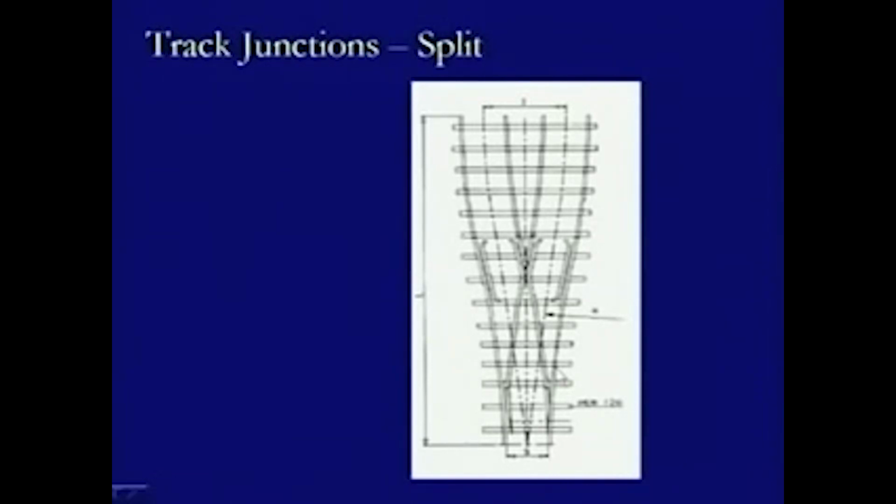than the interlaced sleepers. And here this is the center line of the main track, and this center line of the main track is produced like this, and therefore, at whatever angle it is taking a turn in this direction, the same angle is there at which it is taking a turn in this direction. And because it is symmetrical, we have only one point where the crossing is, and this is the V crossing being provided. There is an acute angle crossing, and at this acute angle crossing we have these as wing